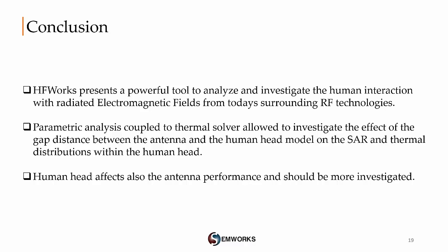During this webinar, we saw how HFWorks presents a powerful tool to analyze and investigate the human interaction with the radiated electromagnetic fields from today's surrounding RF technologies. Also, a parametric analysis coupled with a thermal survey allowed us to investigate the effect of the gap distance between the antenna and the human head on the SAR and thermal distributions within the human head. The human head also affects the antenna performance and should be investigated more in upcoming works.